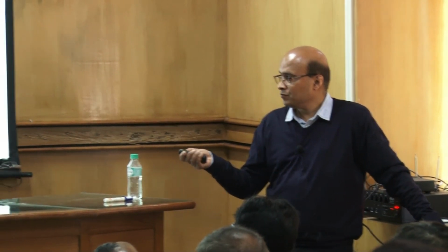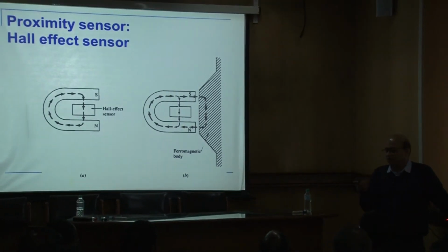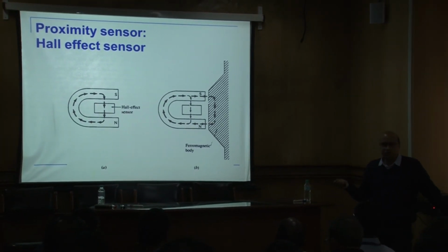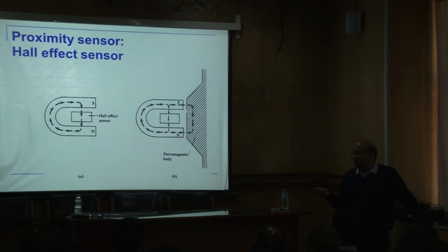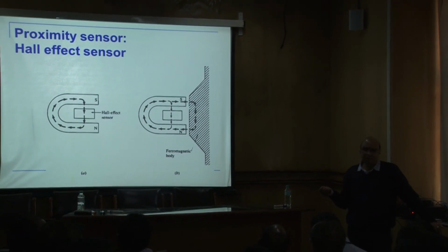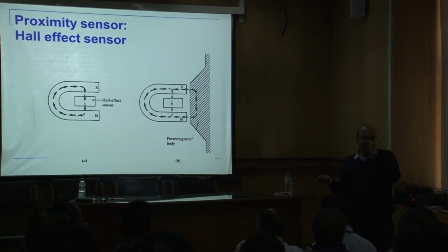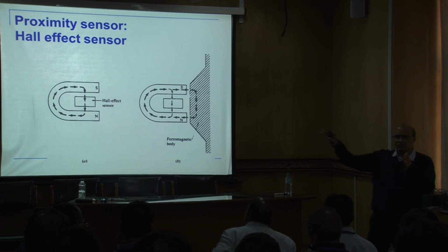Okay. So essentially, what is done is they use the Hall effect sensor. Now this Hall effect sensor is a MEMS sensor. It's very small. It's about 2 millimeter only, and there are no moving parts. So it's a solid state device. It's not very expensive. It's hardly 200 rupees. Yeah. So one is at the output of the engine, and the other one is after the gearbox.